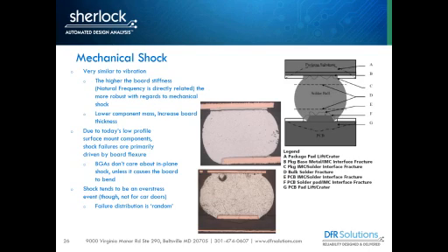And it's interesting about electronics that the yield stress of solder is pretty much right on top of, or overlaps, the overstress limits for a lot of the packaging materials. Bond pad cratering stresses and ceramic capacitor cracking are all within that 40 to 70 megapascals.